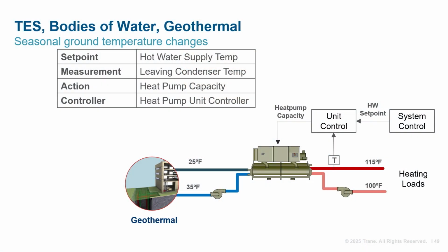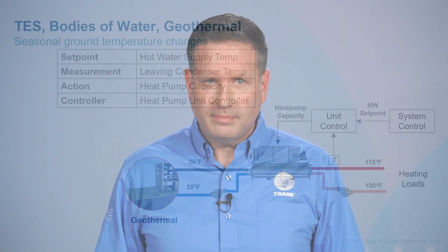At the end of the heating season, thermal energy in the ground is depleted, and the evaporator operating temperature can be very low. This example illustrates the importance of knowing a range of expected ground temperatures to make proper heat pump selections. And conversely, heat pump temperature ratings must be known in order to size the ground heat exchanger.